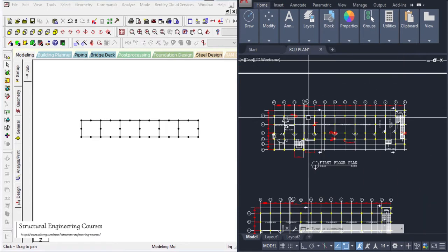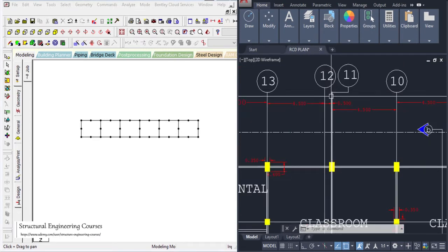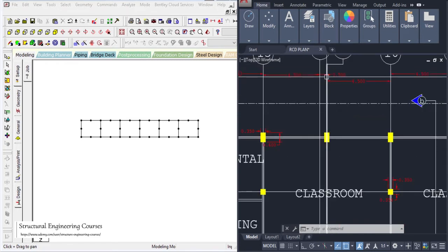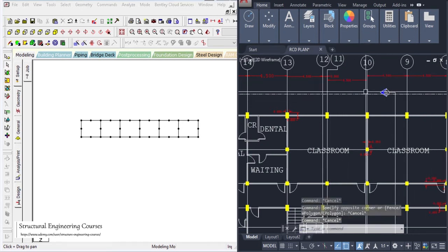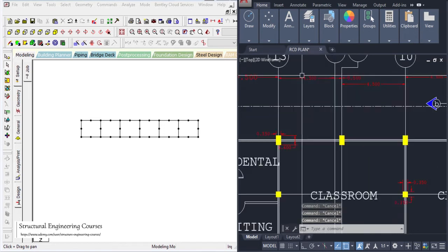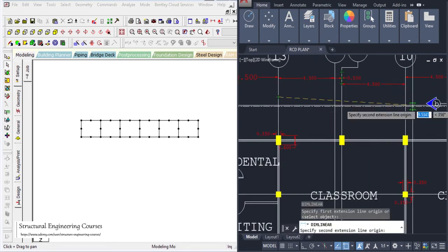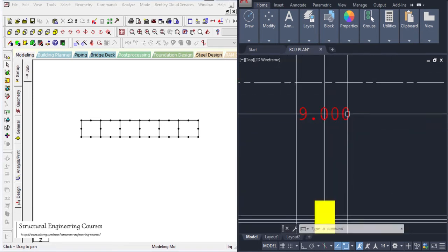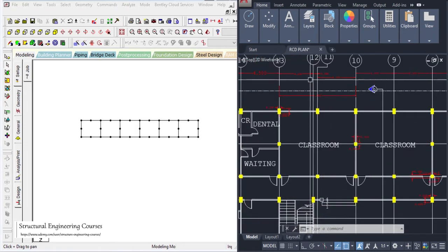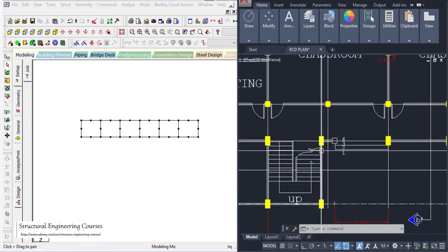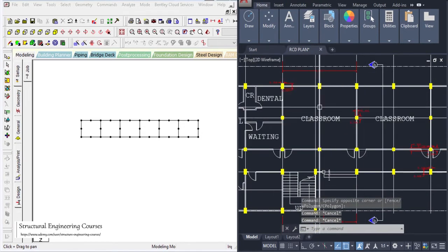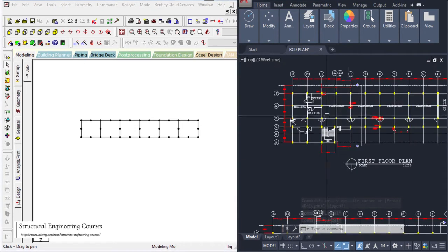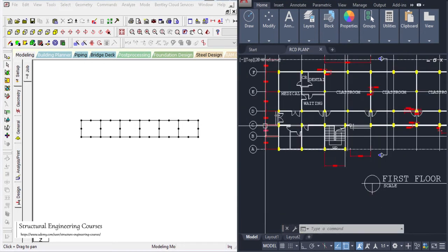So now we have drawn this arrangement, but there is one thing that we should see here. There is this 0.5 meter gap here. So what we can do in this case is that basically the spacing from this point to this point is now 9 meter again, but actually we don't need to worry about this, because this column location is at 4 meter from here. But this arrangement is typical, so this is correct. And after that we do need to model the corridor area also.